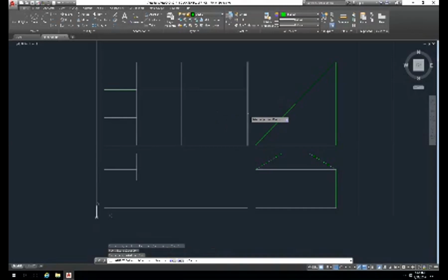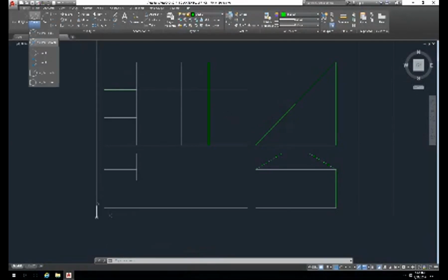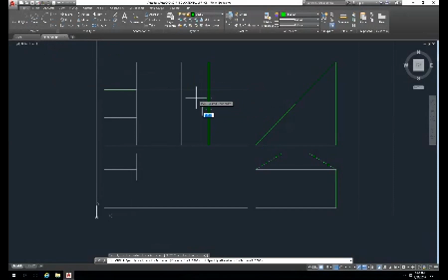Oh, okay. We're still in the offset command. Offset 1.12. Okay, that looks like it is on the object. So press enter to get out of it. And so now we're going to draw a circle with a diameter, because 0.78 is the diameter that we're given. So the center is in the intersection here and the diameter is 0.78. Yep, that did it. Okay.